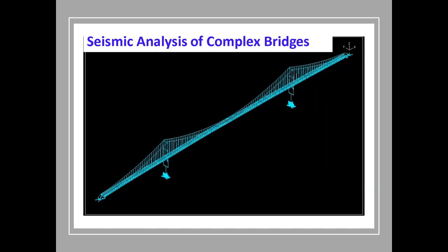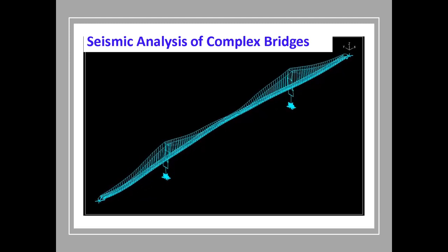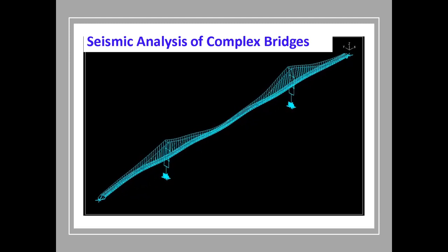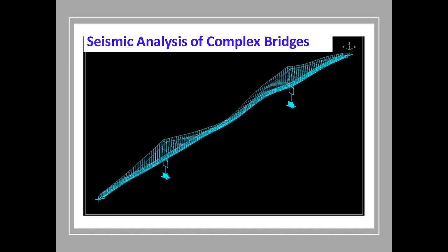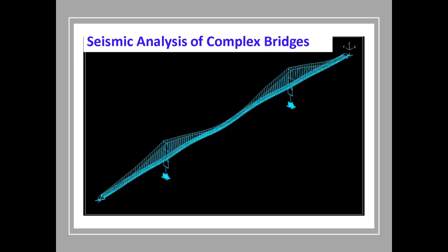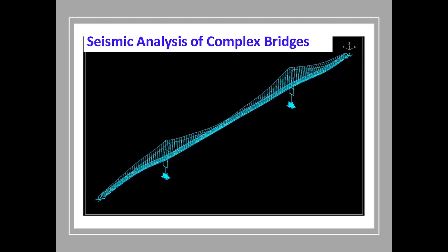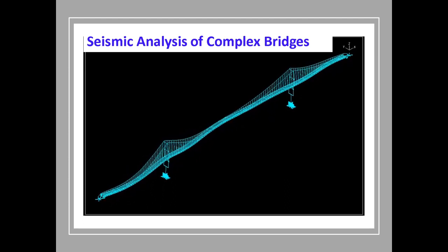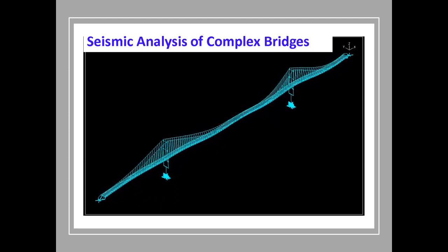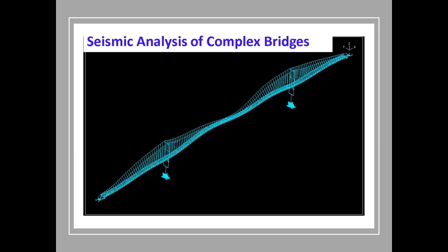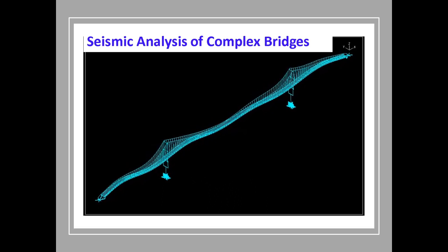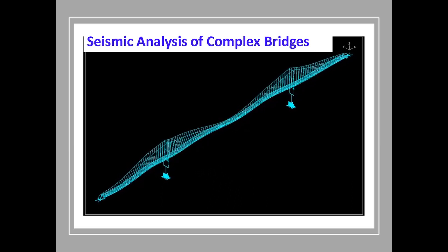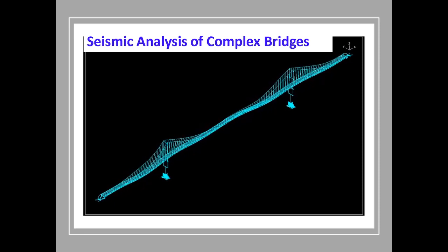Complex bridges have had their seismic design assessed using finite element modeling. The suspension bridge model shown constitutes frame elements for the superstructure, truss elements for the cables and suspenders, and spring elements for the soil structure interaction at the piers and anchorages. At the pier and anchorage foundations, the bridge was subjected to displacement time histories of the near-field incoherent ground motions.